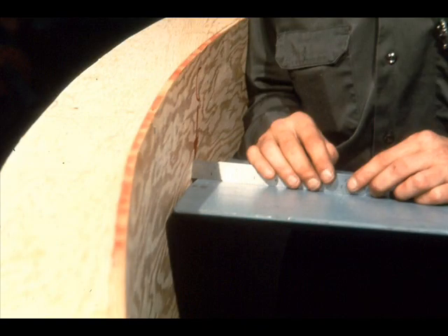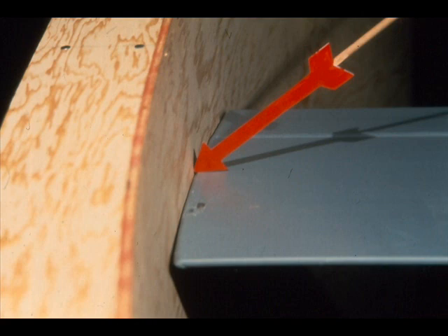The only remaining term we want to pass on is tip clearance. Tip clearance is simply the distance between the tip of each blade and the shroud in which the fan is mounted. If there is no tip clearance, the tips of the blades will hit the walls of the shroud and cause damage. It's as simple as that.